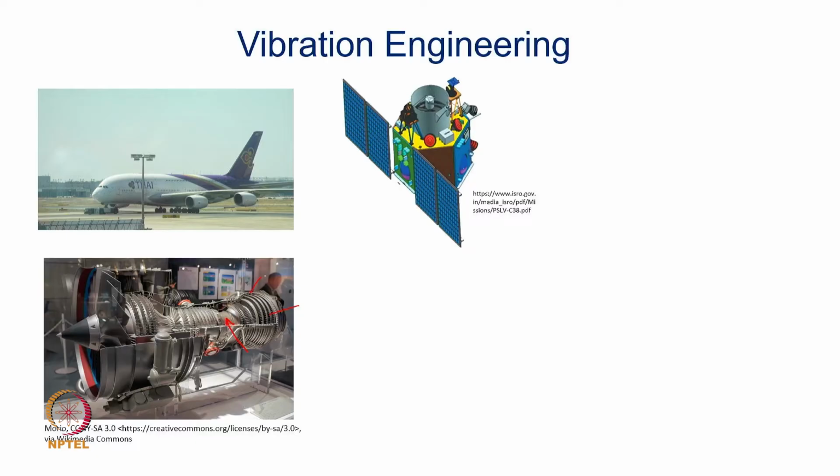The satellite which takes pictures of the terrain on the earth have cameras which are mounted on the structure, and these cameras cannot take high quality pictures if there is even a micro radian vibrations on the structure, because of various components on this satellite structure. There are reaction wheel assemblies and similar other rotating equipment, and if they generate vibrations even with the small amplitude, the vibrating structure can create jitter in the pictures being taken of the terrain. And so that has been a challenging aspect of isolating the camera from such structural vibration.